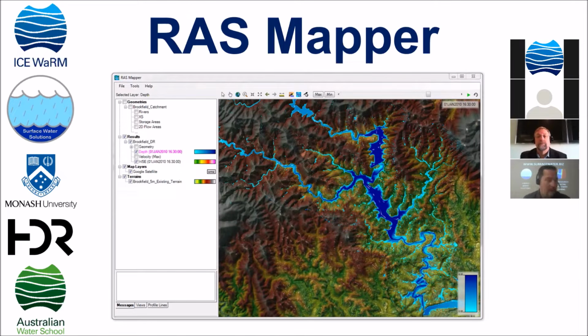Now, what we're going to do now, when we move into Mark's portion, again, I'm not sure if you can see these little gimmicks that I bring along to the course. This is a brownie pan, my wife's brownie pan. What we're going to do now is take this underlying LiDAR resolution data, which can be at a really fine resolution, sometimes 5 centimeter or 50 centimeter pixel resolution accuracy. So we've got that subgrid bathymetry as LiDAR data, as DEM data, underneath this computational mesh. Now what Mark's going to talk about is taking our computational mesh and we're going to overlay it. We're going to squash these brownies down and we're going to be able to interrogate the subgrid bathymetry and put our model on top of it.